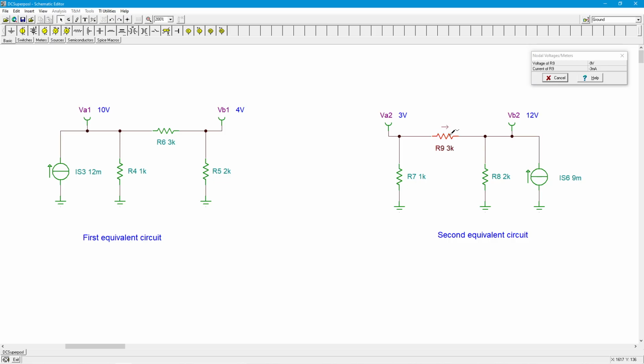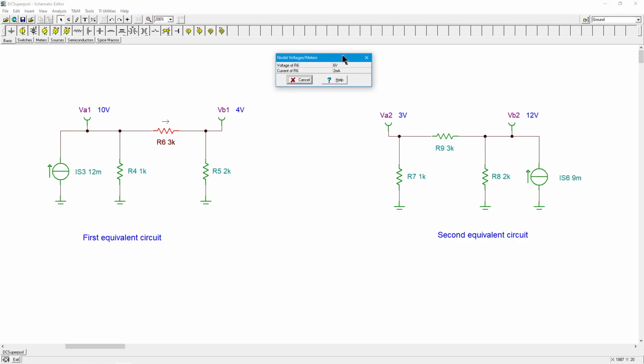So, to find currents, you can just use the node voltages in this case, do a differential voltage and Ohm's law, and you're good. So over here, I'd say, okay, I got 10 volts on this side, right? It's 10 volts from here to here. It's 4 volts from here to here. So it's 10 to 4. There must be a 6-volt drop sitting across our 6 here, the 3K. So you divide that out, and we get, as you can see on the probe, let me bring this over here so it's in the middle, 2 milliamps. So I've got 2 milliamps flowing left to right here.